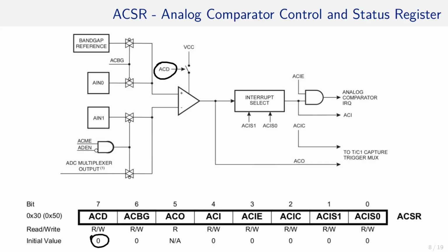That is in contrast to, for instance, the ADC, which needs to be turned on explicitly before it can be used. It will maybe save a few hours worth of debugging time in which a developer keeps wondering why the comparator always returns the wrong result consistently. If not needed, the analog comparator can be turned off so it does not contribute to the overall power consumption of the ATmega. There is no harm in turning it on again, and only if you need to take a measurement.